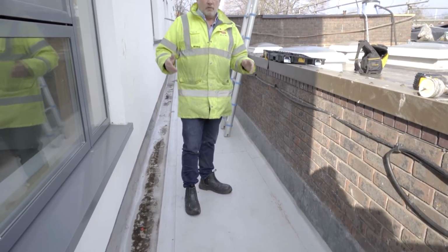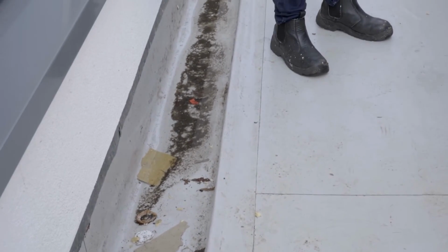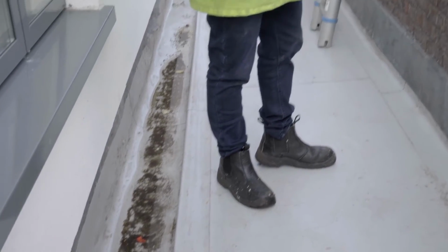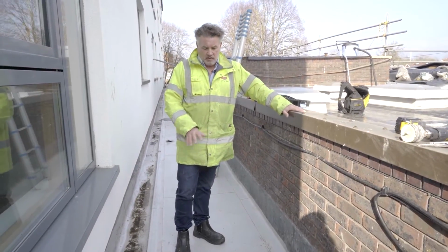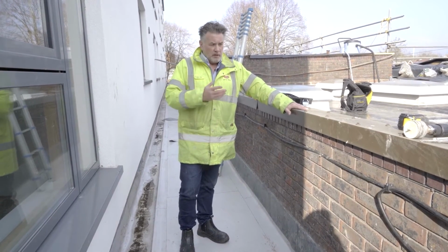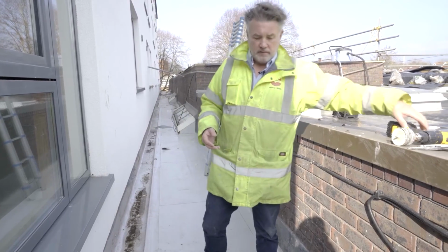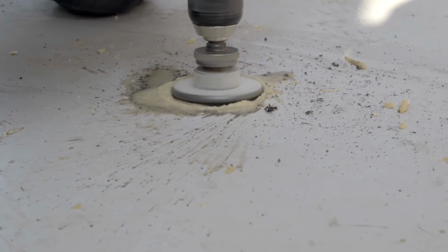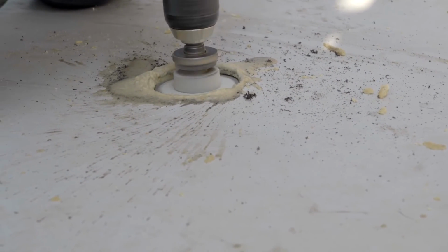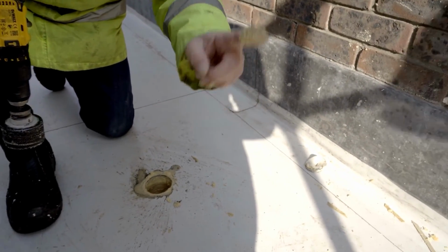Okay, so I've come down to this gutter section of the roof. This is where we've had a particular amount of water come internally, particularly around the skylights, but I suspect that this insulation that's inside here is wet, but I'm going to do another core drill to determine just how much, or if any. So I can see already there's quite a bit of water coming out, and it's spraying all over. This is the insulation.